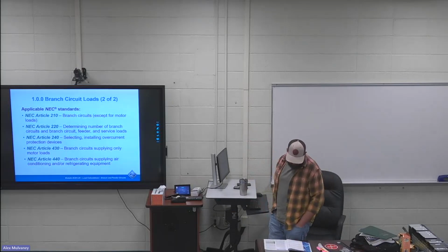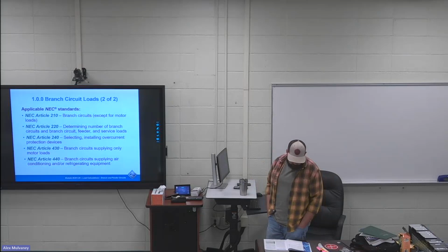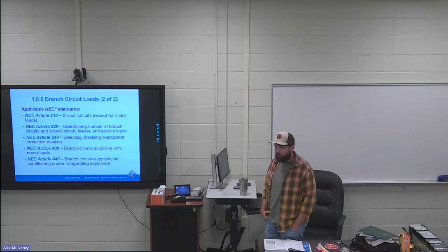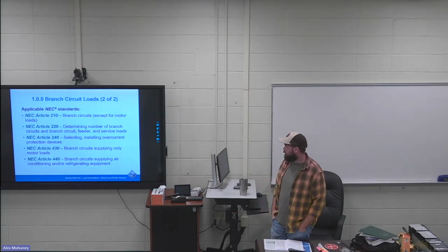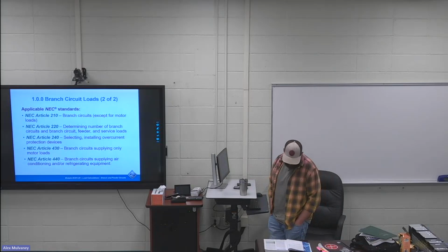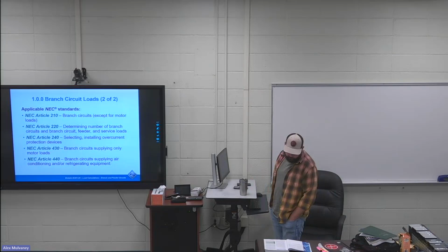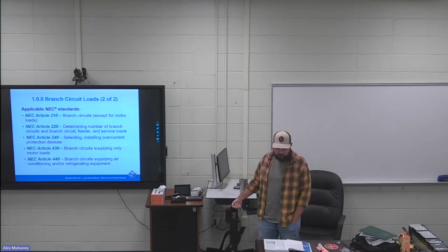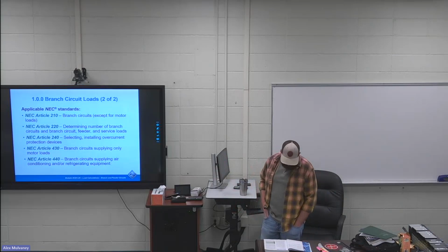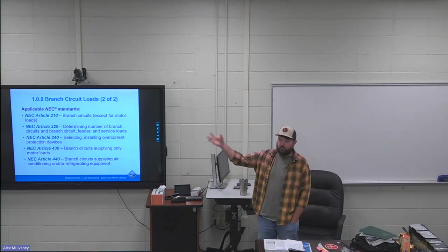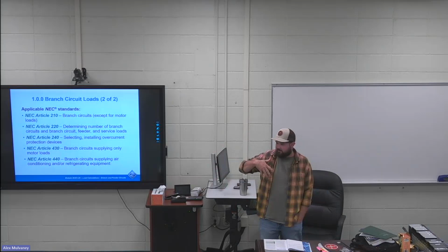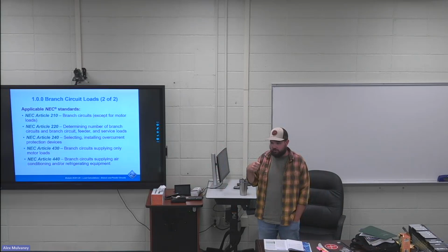You need to know what these are. Ampacity we've talked about, but ampacity is the maximum current that something can handle. So that would be its ampacity. Branch circuit you've heard, but it's the circuit conductors between the final overcurrent device. Again, what's the final overcurrent device more than likely? A fuse or a breaker. Protecting the circuit, so that's from your breaker to wherever your circuit is. Say it's wall outlets or something like that. That's the branch circuit.